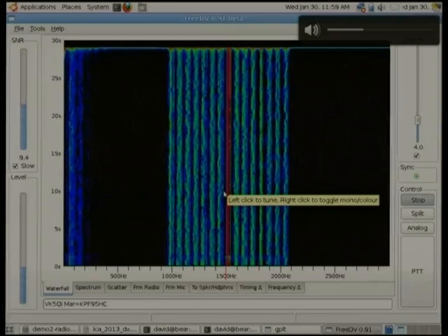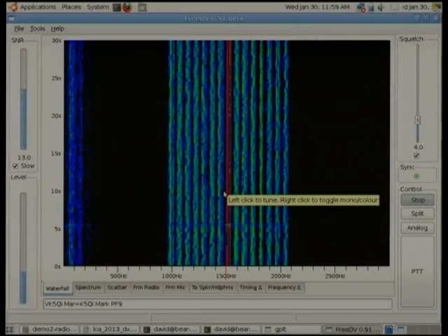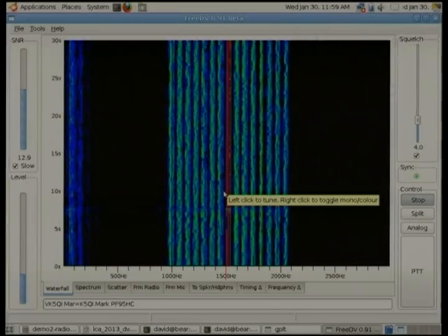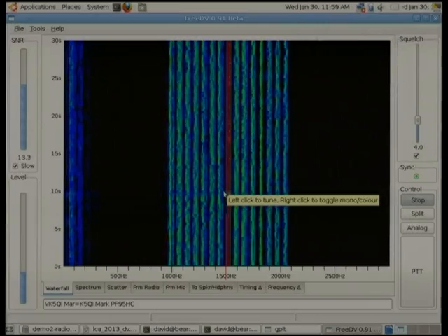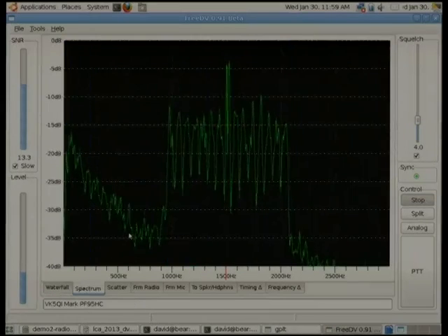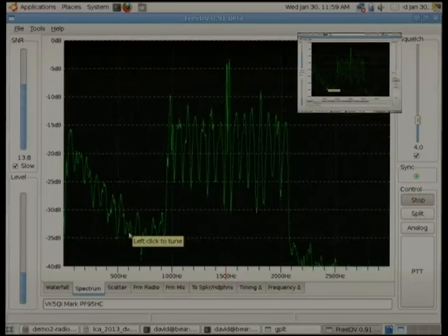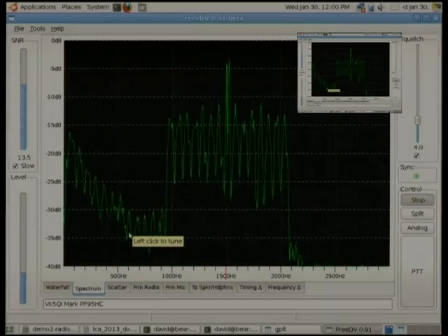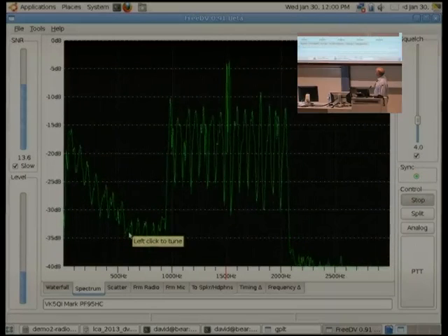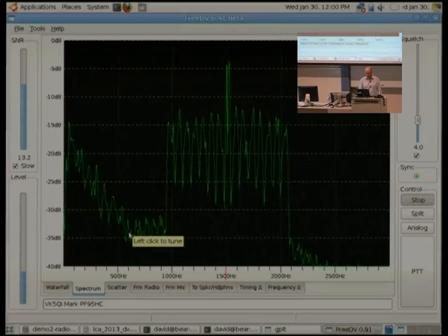So I'll just turn that down while I explain what's going on. So Mark's transmitting over there, I'm receiving. What we've got up here is called a spectrogram, and that's just showing a rolling time plot of the spectrum of the received signal. What's actually coming in off the air, that's the spectrum there of the modem signal. That's what we call a parallel tone modem. There's actually about 14 carriers that we're receiving there, and then demodulating. The centre big spike in the middle is some synchronisation information.